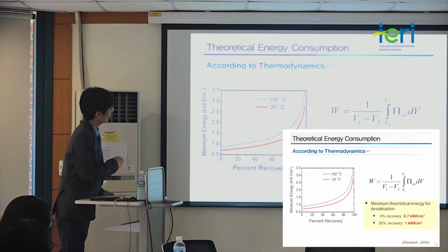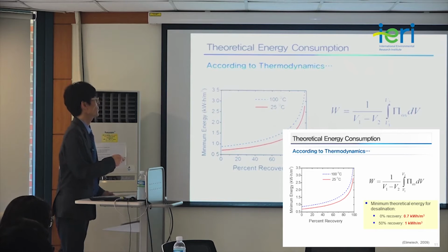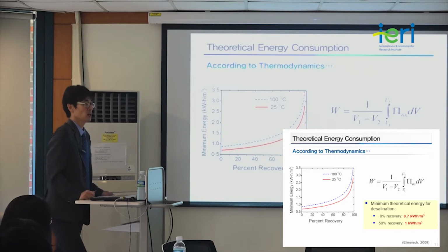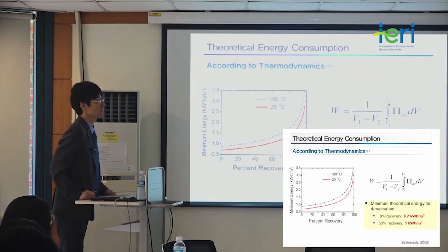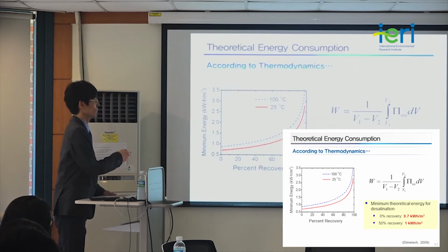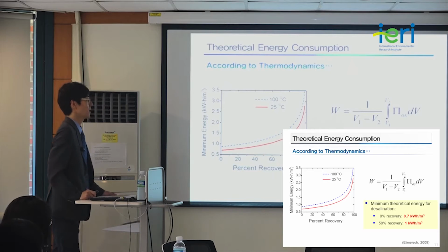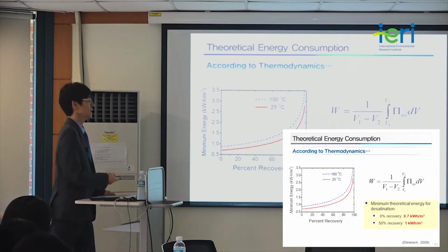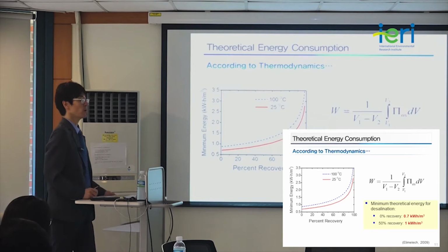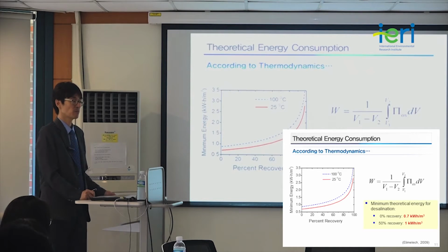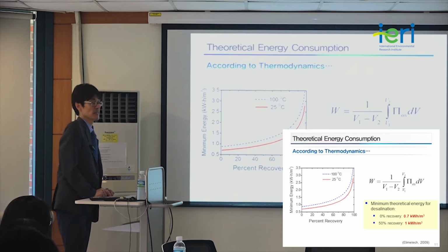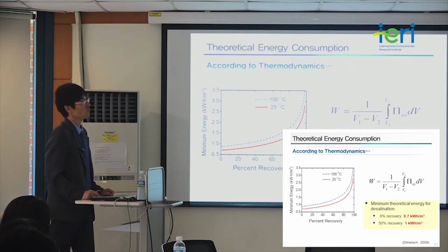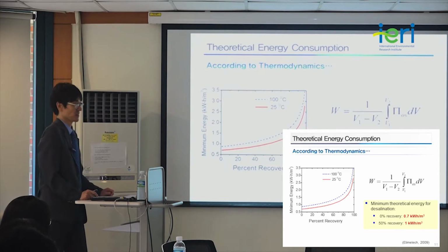Another case is if you have higher temperature, in such cases, according to the Van 't Hoff equation, which has the temperature term in the right side, this osmotic pressure will increase. But this effect is negligible because in many cases, with seawater, we are talking about the temperature between 15 Celsius degree to 40 or 45 Celsius degree.